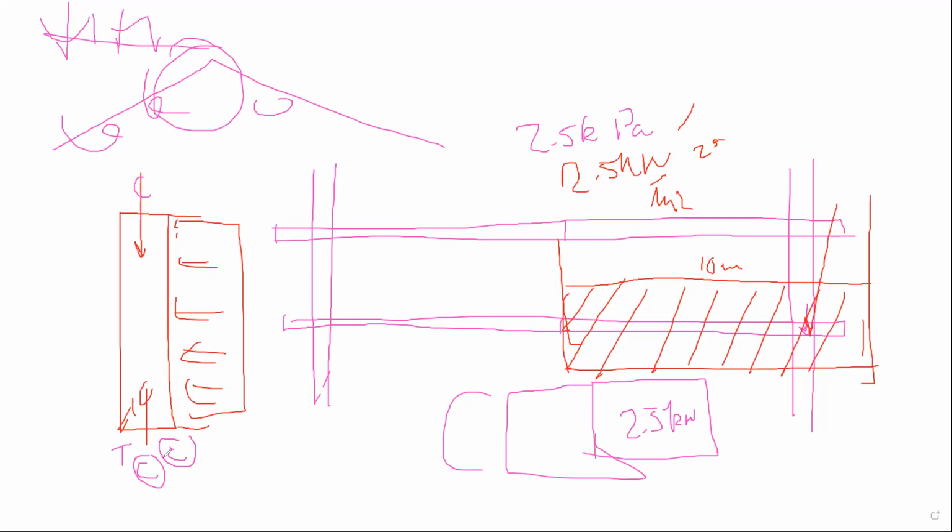And that's why you have that interaction equation. That's why you have PF over PR: that's for this compression here. And MF over MR is for that compression there. That's what you're actually calculating. You're making sure that the ratio of this and the ratio of that, when both combined, don't exceed the actual resistance in compression right at that point, because that's where they both combine and overlap to cause the total stress on the member.